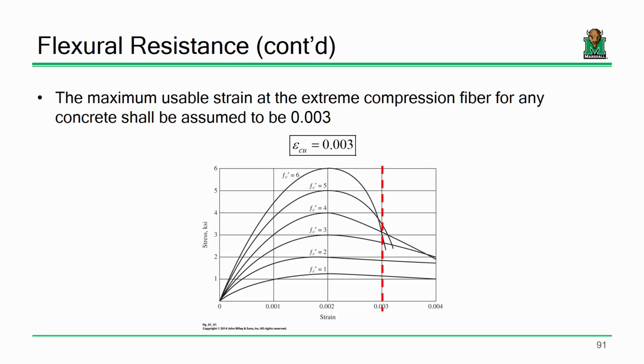Now, I guess we could be a little more accurate. We could develop a model or an equation that better calculates that for different grades of concrete, for different mix designs. The problem with that is there's something to be said about taking concrete design and making it too complicated. You want to keep it straightforward, and you want to keep it applicable. You also have to look at the ramifications. Ultimately, we're making a conservative assumption about the behavior of the concrete, because we're going to use this assumption just to make sure that the steel yields. So it actually makes sense to be on the conservative end.